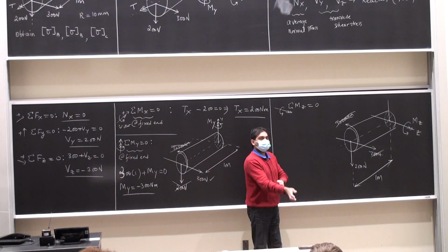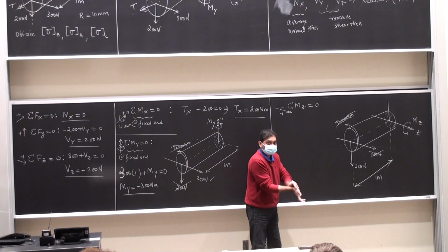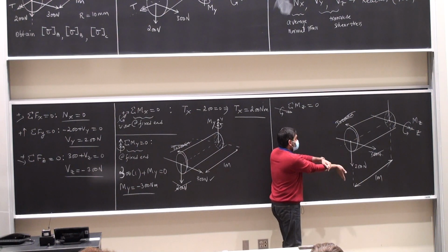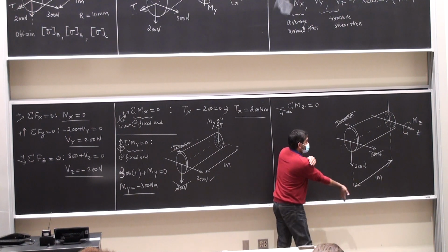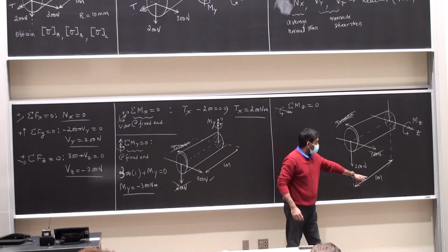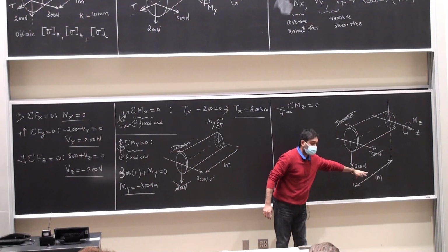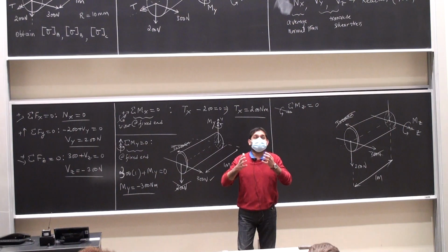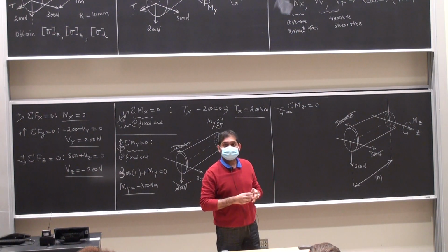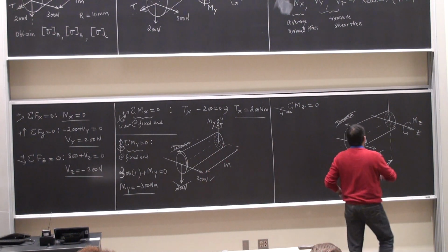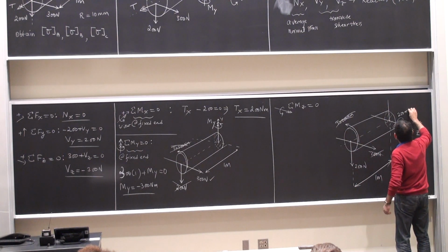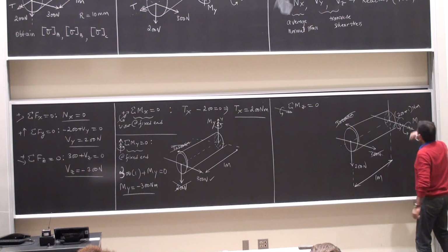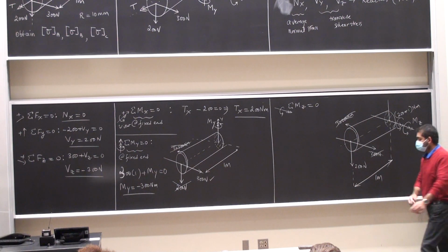Slightly tricky to use the right hand rule because I can't contort my hands in that manner, but I hope you get the idea. My fingers are pointing vertically down, along the direction of the force. My palm is facing the z-axis. If I curl my fingers, multiplying the 200 Newton force by a distance of 1 meter, I will get a moment in the positive z direction. That's what is going to end up the case.